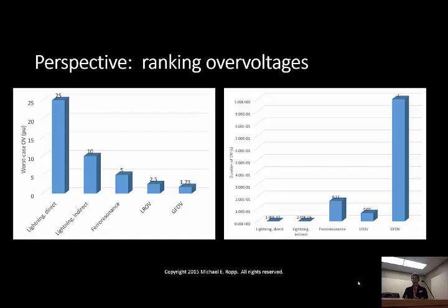And what happened was they had a GSU transformer that went up to, I'm going to forget the voltage, I want to say it was 230 maybe, but it was a transmission voltage. And the high side breaker on that transformer popped. So the PV plant was isolated with only the capacitance of the underground collector system and the shunt inductor, the nonlinear magnetizing inductor of that GSU transformer. And that, big capacitor, nonlinear inductor, that's where you're going to get ferroresonance happening.